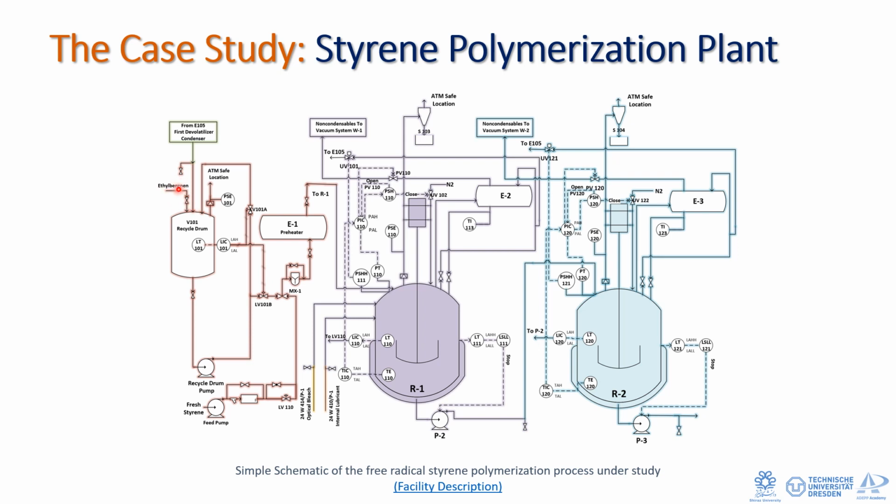Solvent is also added to the reactor to control the content viscosity and reactor's temperature whenever its concentration decreases in the reactors. In node 2, the process of the first reactor polymerization is completed by 35%. Reactor is protected against the runaway reaction by the inherently safer design of condenser E2. In node 3, the process of the second reactor polymerization is completed by 60%.